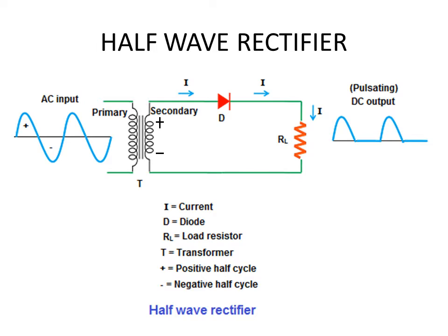So even after rectification, the output contains a fluctuation which is rhythmic, similar to a wave, and therefore it is like having an AC component at the rectified output. We will later find out how much ripple is present in the rectified output. A ripple is the AC component present in the output. So ripple factor is the ratio between the AC component and the DC component in the rectified output.